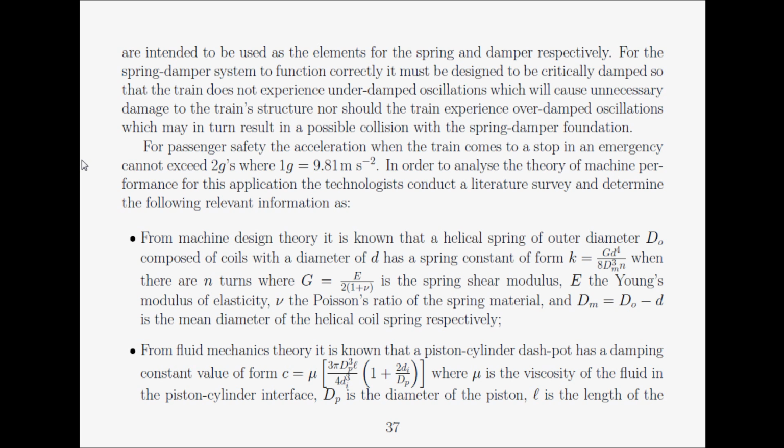and the wire has certain geometrical parameters, a wire thickness, a wire length, and there are various formulae that you can use to work out the equivalent spring constant. Over there is a formula that you can see in your slide. K is equal to G d to the 4th power over 8 D m cubed n, and there are various explanations in the question about what each particular term means.